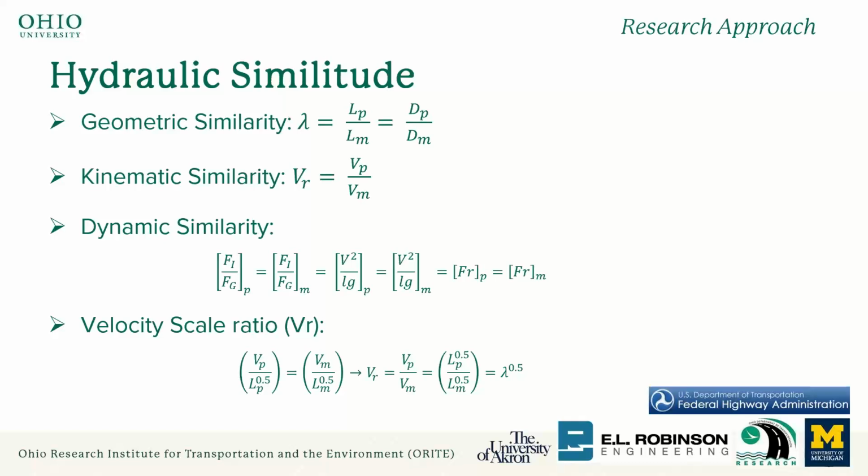That's standard in laboratory hydraulic experiments: to use Froude scaling, because that's the scaling that produces equivalent thresholds of motion for any object, meaning where the lift force will overcome the gravity force, or where the drag force will overcome the friction force.